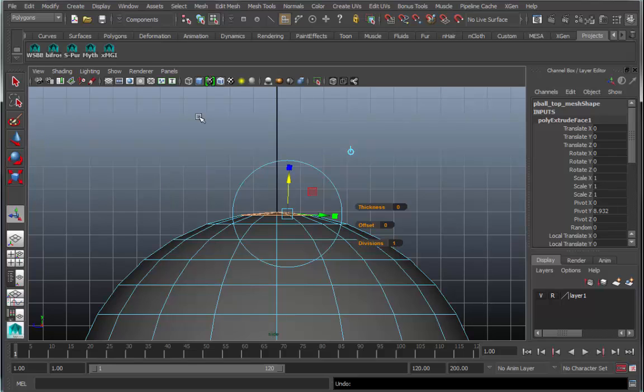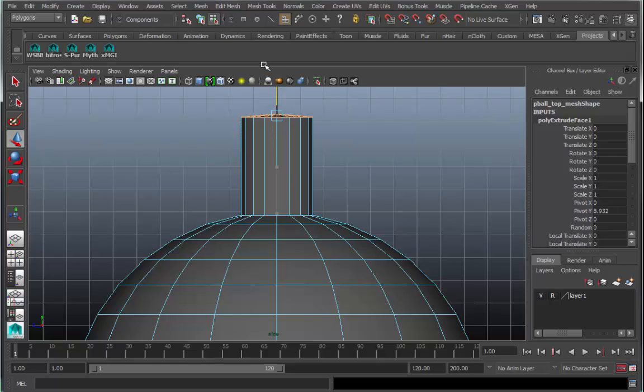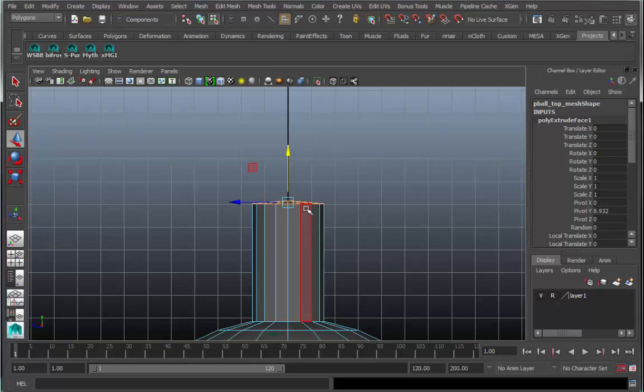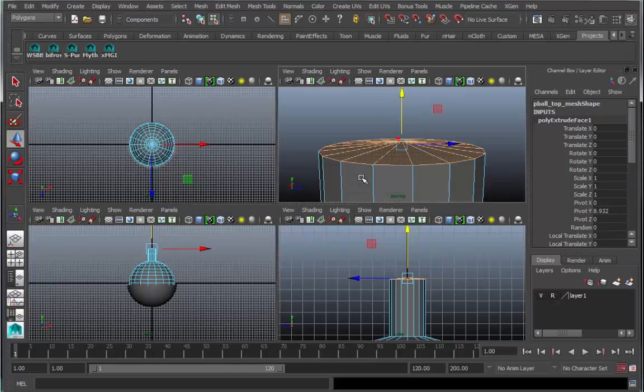Do not click off anywhere here. It will deselect these faces. So if you click on the move tool, you now have a control that allows you to bring just those polygons up. I'd like to have them dragged up about, let's say, 1, 2, 3, 4, 5 units up, roughly. Can we be exacting? Yes. If we hold down the X key and make sure to grab just the arrowhead that's going straight up, we can actually snap these. I'm currently snapping them so that they're about the level of that grid line. And with them selected now, I press delete.